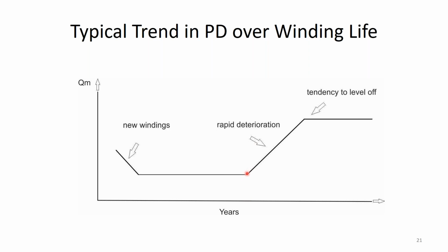But then, hey, the oil leaks into the machine, the windings get loose, they start vibrating in the slot, grinding away the insulation, getting lots of slot discharge, but it doesn't continue increasing until it fails. Unfortunately, we've learned, and we've had many false negatives because of this, where we thought a machine was good, but in fact it wasn't, especially in the days before we had our alert levels. And it turns out there are various physical mechanisms, or theories I propose, but it's something we actually do find, that the PD just stabilizes. It doesn't continue to go up. In fact, sometimes it even goes down.